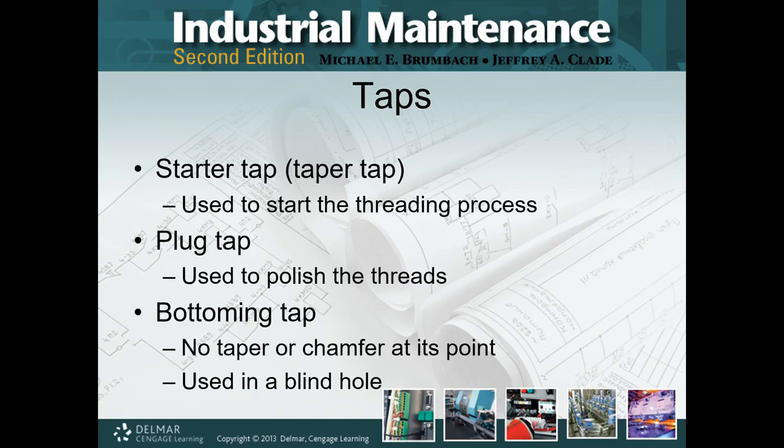I have only a few bottoming taps, and these have like no taper. I think technically there's two threads that are tapered or chamfered. That's it. These you cannot start. You cannot really start a hole efficiently and get it threaded by using a bottom tap.